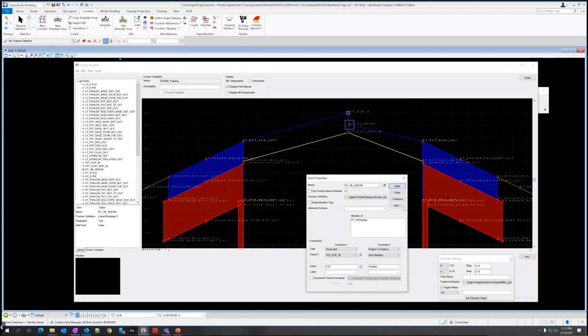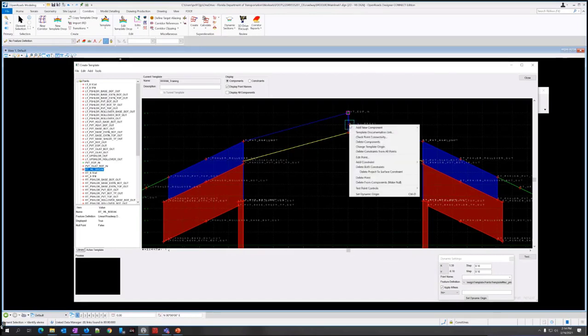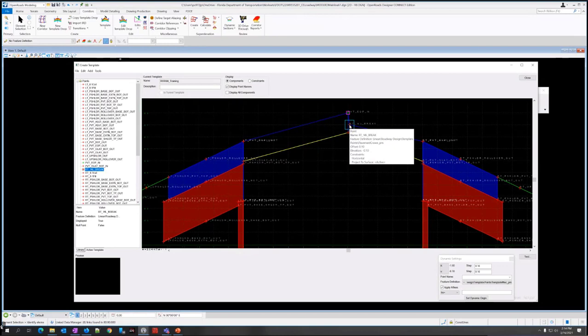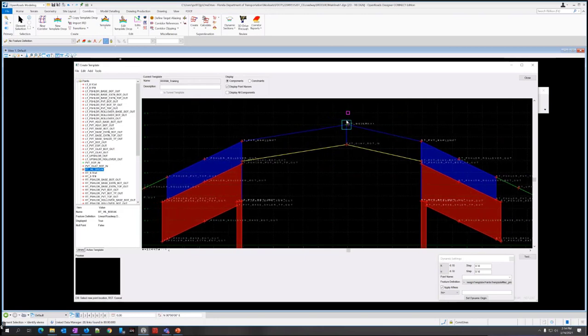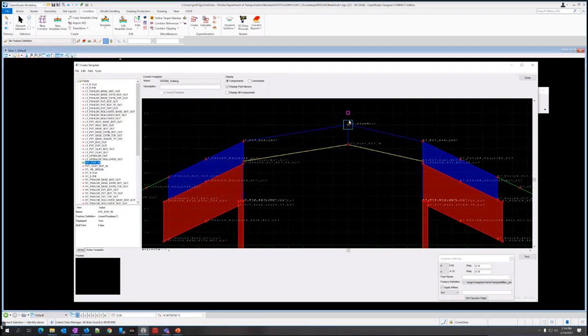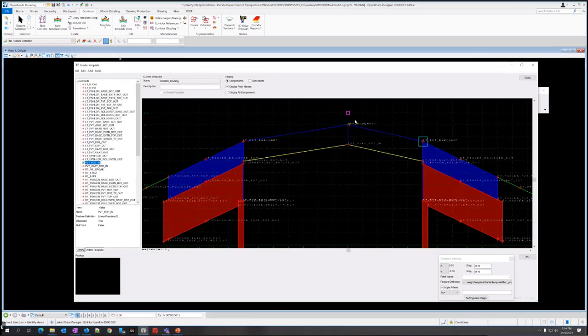Now, this looks a little bit ugly. Like I said, because we did the projected surface, it is just keeping the same location. And unfortunately, you can't actually move it. What you can do is move this point. I'll move that down there. So the green one is the only one that's not constrained, so I can move it. If it's fully constrained, I don't have an option if I right-click to move the point.